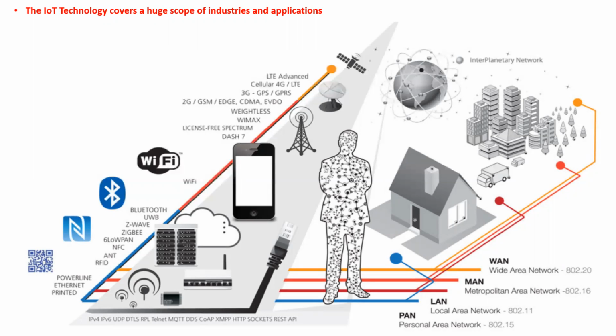If you look at this complete diagram, the communication will happen over the PAN (personal area network), LAN, MAN, and WAN. So these are the networks it is going to use in this particular communication framework. And when it comes to sharing of data, they will be using RFID, a radio frequency identification system. It attaches to the objects to be identified. A two-way radio transmitter-receiver, called an interrogator or reader, sends a signal to the tag and reads the response.